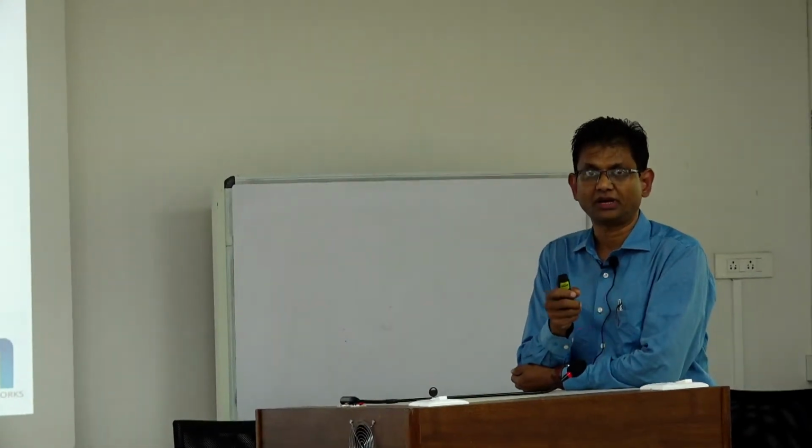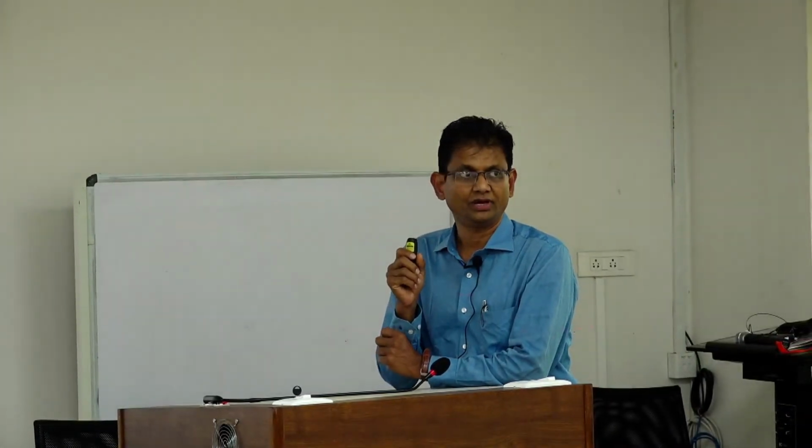As I said, all those processes in optoelectronic devices are based on excitons. You might have already heard what an exciton is. An exciton is nothing but a bound electron and hole pair. When light hits the semiconductor, the electron goes to the conduction band, but the electron and hole are still bound, not separated. That is called an exciton. After diffusion, the exciton will dissociate and separate into charges.